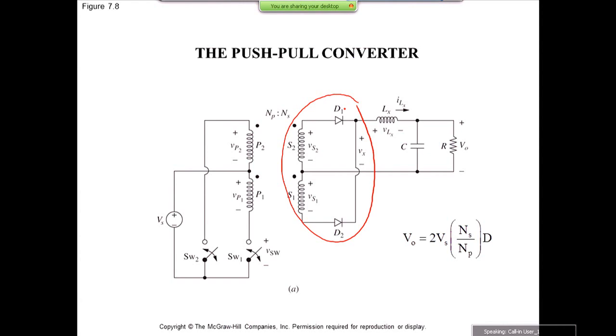The trend is, using the switches on the primary side, you try to create some sort of square-shaped signal applied to the primary windings. And remember, we are talking about the transformer. On average, this signal should be 0, otherwise the transformer is going to get saturated. On average, there should be no DC bias for this signal, and there is none. So this is my 0 level. Using the switching manipulation, you are creating this kind of AC signal.